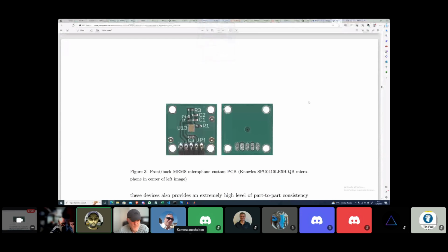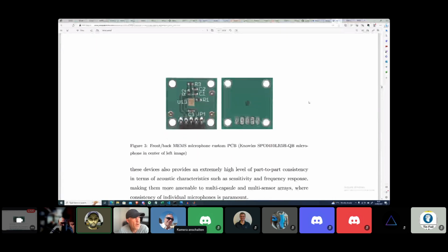Richard, let me help you. Bojan is right on this point. The way the sensor works is you have a diaphragm and the hole, and the diaphragm moves based on the mechanical frequencies of sound. So it will only come from the direction where the hole is. It will not come from the other side. Okay, so it's not omnidirectional, but hemispheric. No, it is omnidirectional, but it's omnidirectional from where the hole is. That will cause the diaphragm to vibrate, and that's how the microphone can capture the data.